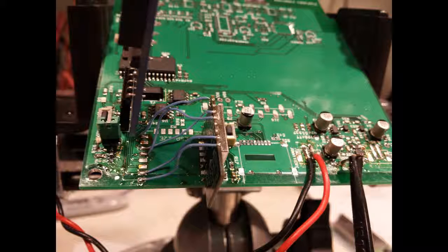to put a tantalum cap on the input for the VCC on the radio, and that thing was causing oscillation on the power supply when the radio would turn on. But I didn't find that until I'd pulled almost all the parts off the board that I just put on, because I couldn't identify where the actual power supply problem was.